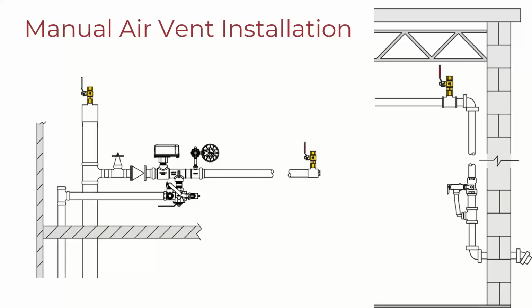we highly recommend that you note somewhere on the plan or somewhere in the building, near the general information sign or in a location that is easily visible, where these manual valves are located. It can be very problematic if you have installed manual valves and have not provided their location, since they can be kind of small. And if they're installed near a high point in the system, they're not going to be easily visible from the floor. So you're going to want to make note of where these valves are located if you expect someone to actually be able to manually operate them.